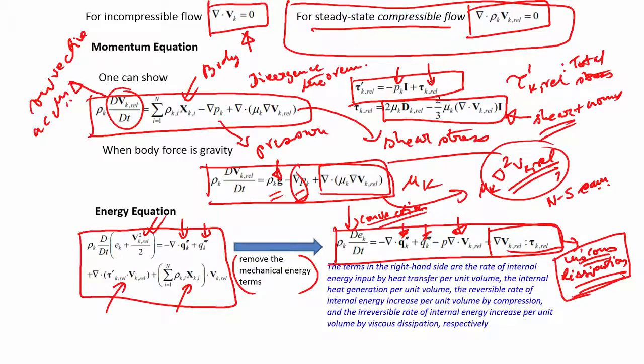Why is that burn happening? That is happening because of viscous dissipation. So, why is viscous dissipation important? This is basically the work done by the shear stress. The work done by the shear stress is a lot higher when these two fingers, which represent, in the analogy of two parallel plates, are like two parallel plates. So, naturally, the heat that is generated when the flow goes through these two fingers of mine is a lot.